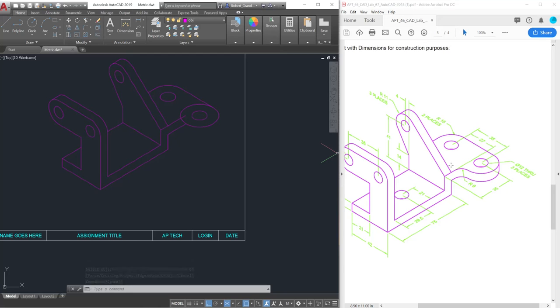There are some issues here that I want to think about carefully. So if we do the math here and subtract 27 from 35, we know that the distance from this line here, which is the edge that you see here on the object, to the center of this is going to be 8. So there's a radius of 8 here. So that means that this circle here, since it has a radius of 8 and it's tangent to this line, the center of this is directly in line with the center of this one, as seen in the top view. So what that means is if I simply took this radius of 8 circle and placed it here, I can then move it, the combined radii of this radius and this radius, to its correct location.